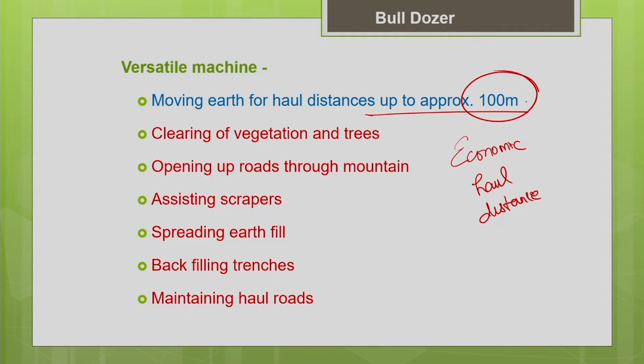The actual distance will depend on the size of your machine, the size of your dozer, and the type of material which the bulldozer is going to push. If you are going for a bigger tractor or bulldozer, the economic haul distance may be slightly higher than this. So the actual distance depends upon the size of the dozer. The greater the dozer, the more the economic haul distance will increase.